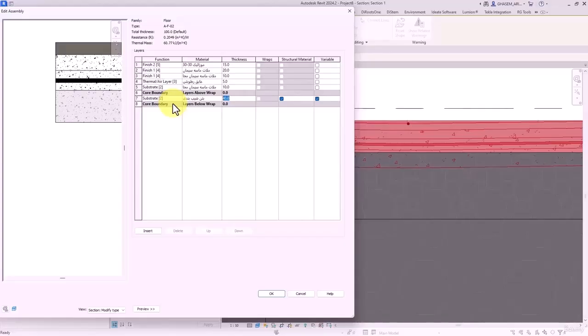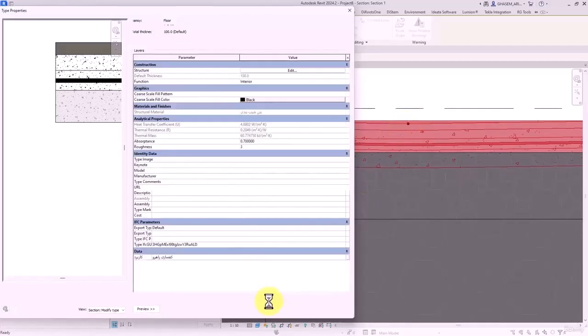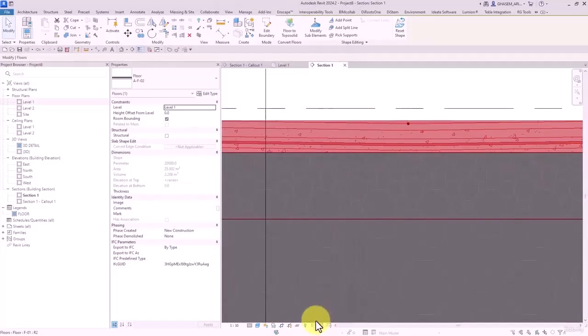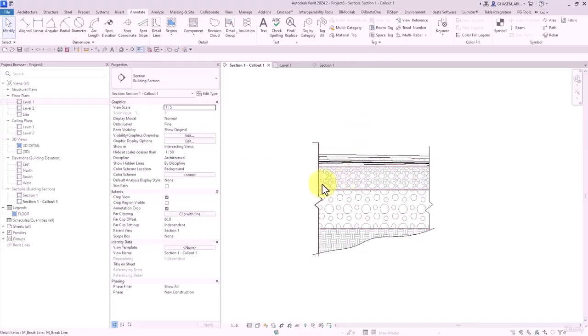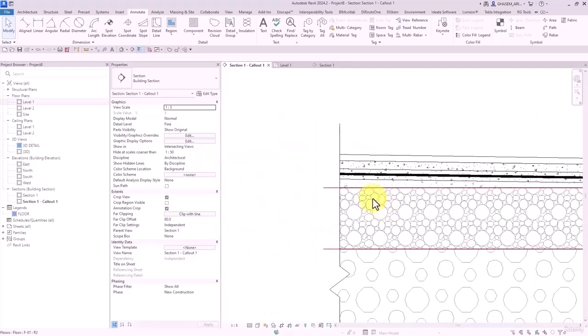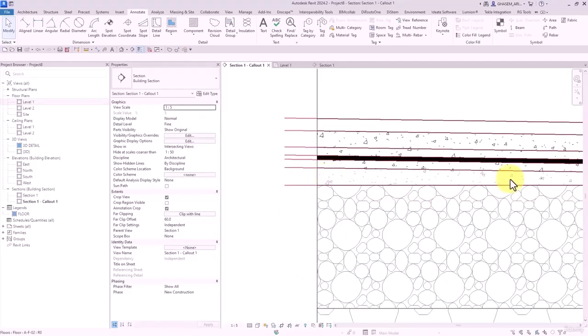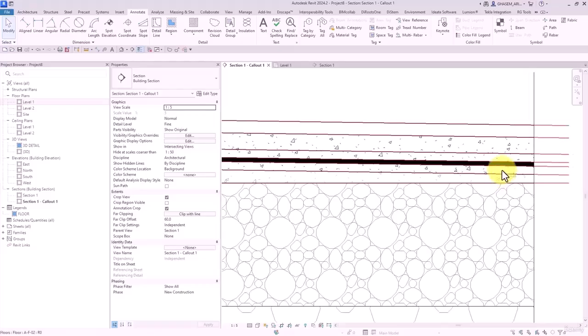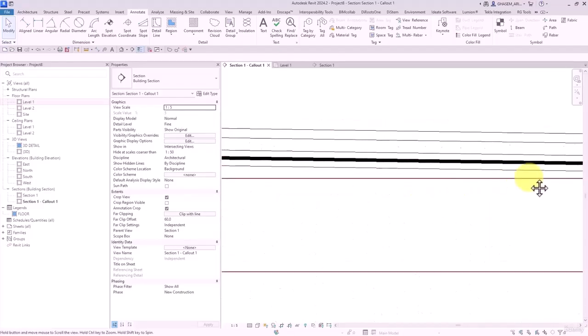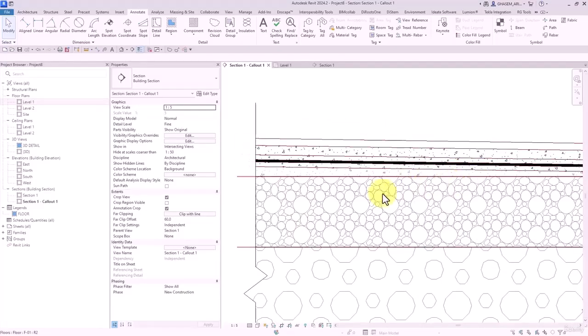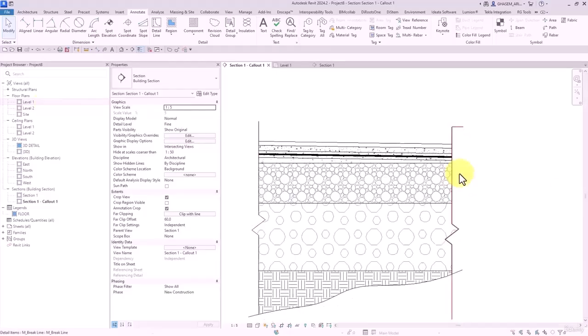Another point is that the value which you have here should not be bigger than the thickness of this substrate concrete layer. For sure, when it's bigger, everything will be reset. It will be changed to defaults. Okay, it means that from this layer downward, it's flat, but it's continuing this slope when it's upward. And when you look at here, you see that this layer is variable. This thickness is changing and it's obvious. But the thickness of other layers is fixed. And that's it.